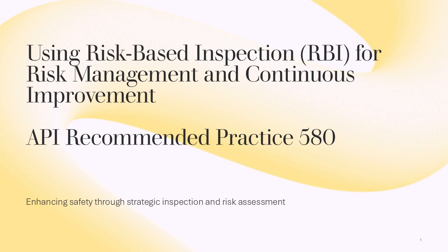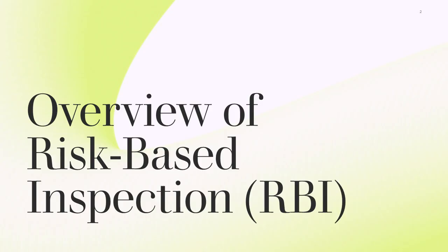Using risk-based inspection, RBI, for risk management and continuous improvement per API 580 recommended practice, enhancing safety through strategic inspection and risk assessment. Fundamentals of RBI and its role in engineering risk management.